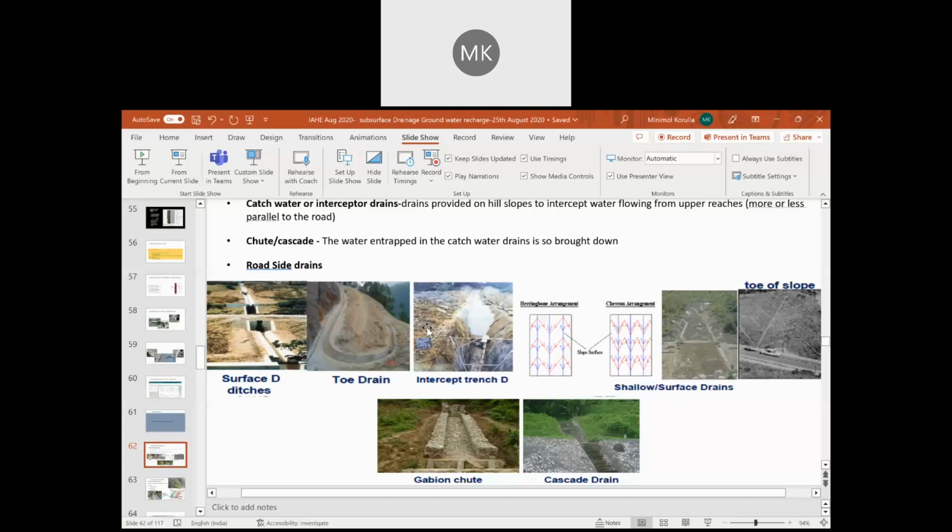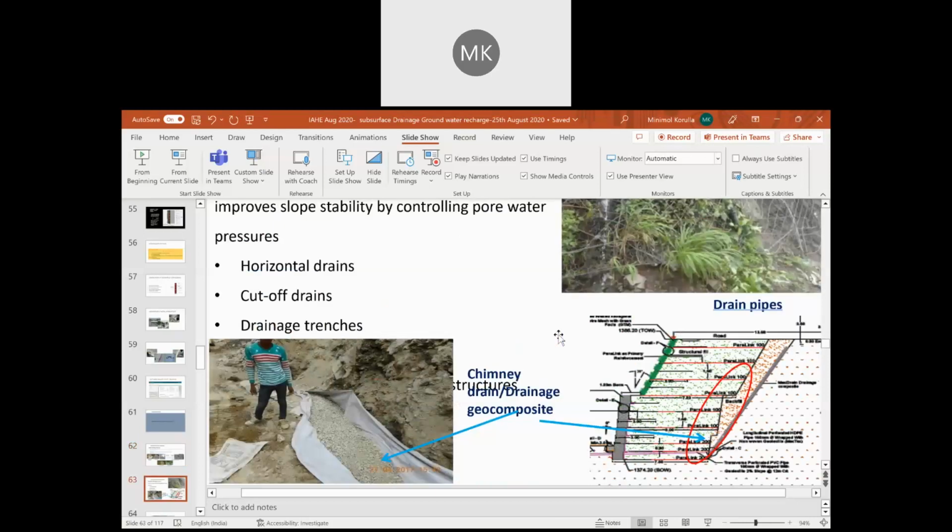Now, fin drains. Okay, so the French drain, we have gone through that. What is a French drain and how simple it can be? It can be with pipes or without pipes. It will normally be a roadside drain where the aggregates will be there and a geosynthetic enclosure or encasement, which will be a geotextile. So it is like wrapping with a fabric.